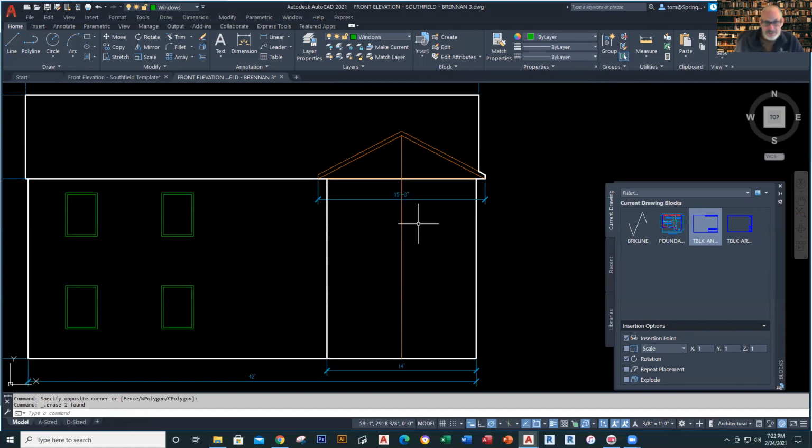And then over here, I can actually start to do the same thing. I can put these in over here, and these are actually 3 foot 6 from the side. So I'm going to make a line. I'm going to go here and go over 3 foot 6, boom, and then up 2 foot 10, like that. And I'm going to copy this over here. I grab from the bottom and plant it right here. All right, there we go.